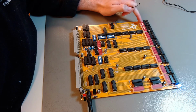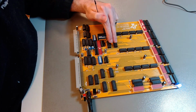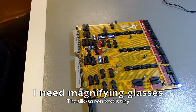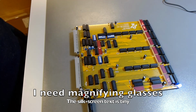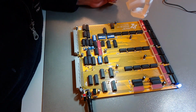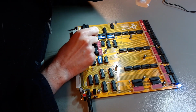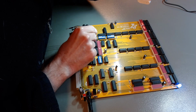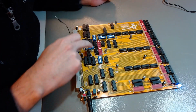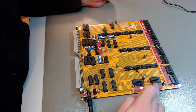So let us now load the contents on the bus on the jump address registers, and they are visualized here. The registers are these two chips, but they are visualized here. Let me get my little device to see better. So okay, jump address high load enable, and jump address low load enable. So if I press clock now, these two values should go into the jump address register, and there they are.